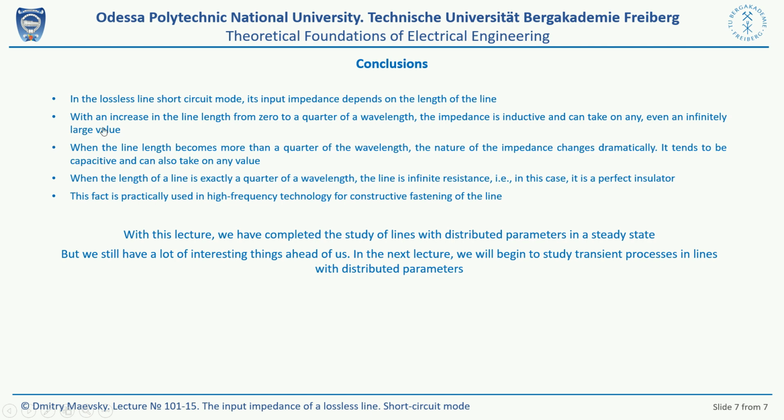With an increase in the line length from 0 to a quarter of the wavelength, the impedance is inductive and can take on any, even an infinitely large value.